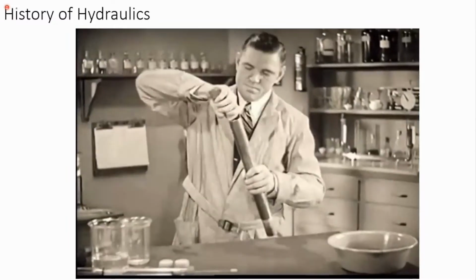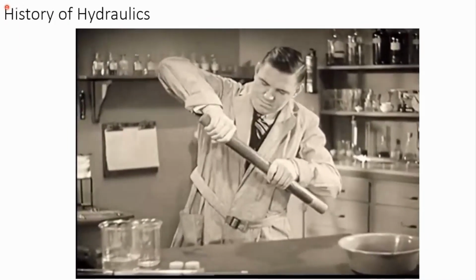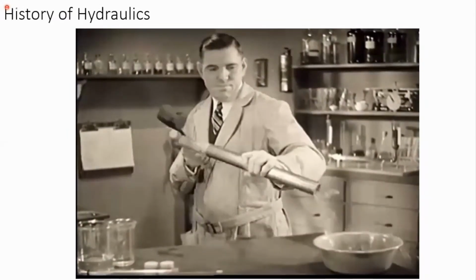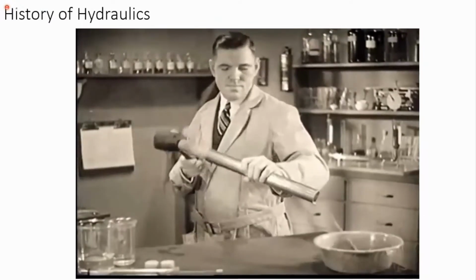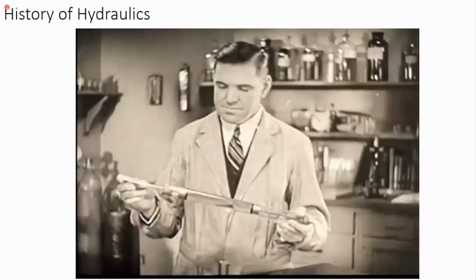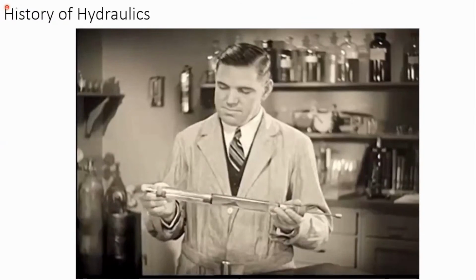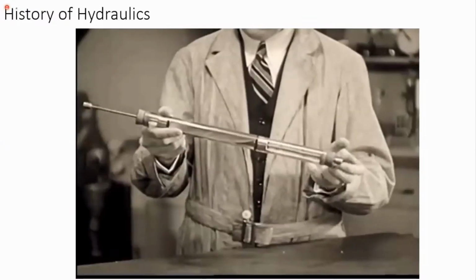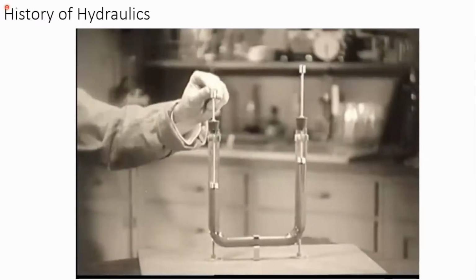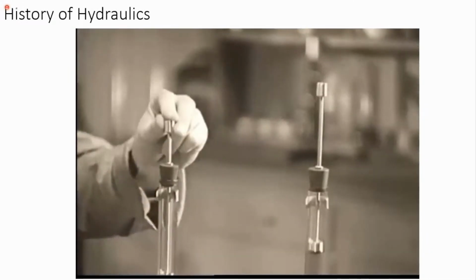If you take a piece of ordinary pipe and fill it with liquid and put a plunger at both ends, any blow on one plunger sends the other plunger flying out. Liquids can't be compressed, so here's what happens inside. The power of your blow is transferred to the other plunger by hydraulic transfer of power. This is the simplest kind of hydraulic system. Bending the pipe doesn't affect this transfer of power at all. It goes around corners just the same.